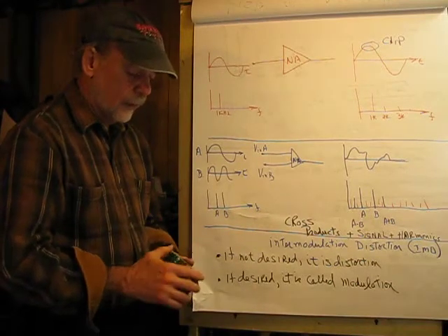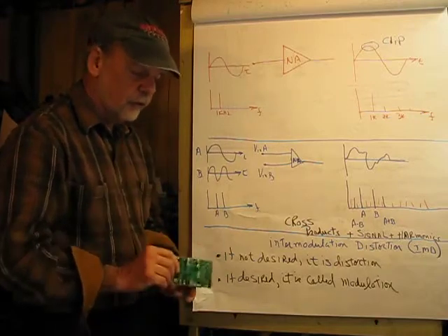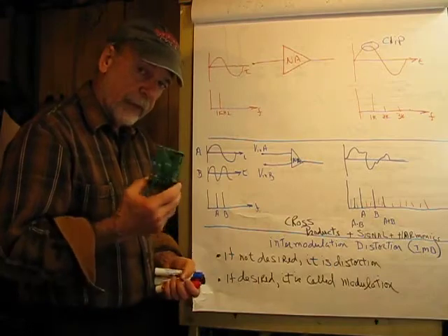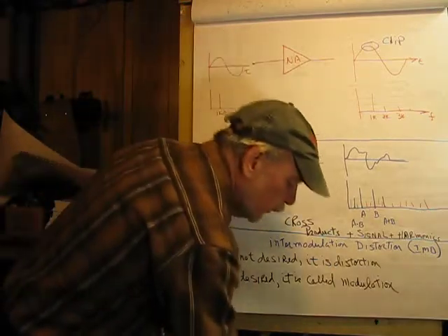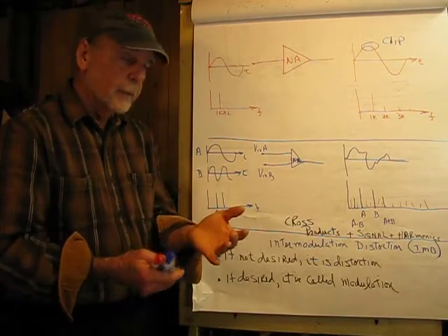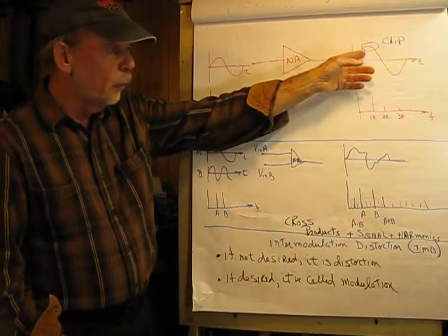And suppose that we're listening to music through this, which is one of the functions of it, and we're pushing it kind of hard, and we're near the end of life on battery, so the operational amplifier that's driving the headphones is running into the supply rail. So that would be like 2.8 volts.